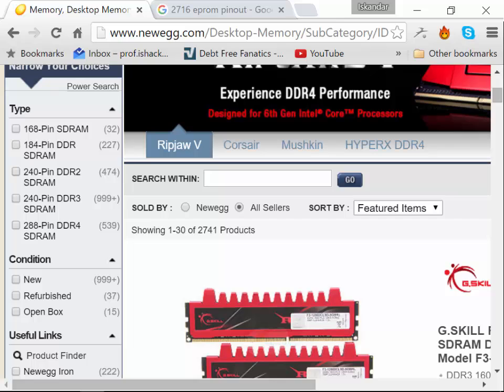When you take the power off, what's stored in a ROM is kept there. If you take the power off the most common RAM chips today, the contents are lost. So really the key thing is not the read-write as much anymore. It's the volatile versus non-volatile, because ROM today is also read-write.